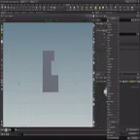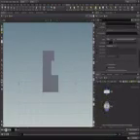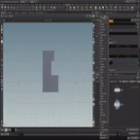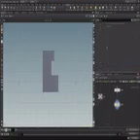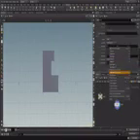Then I want to place a fuse, because we're gonna place all these points onto a grid. So let's set this to grid, and let's add a null node. And this null node is going to have the grid size. So let's call this grid size. So there we go. And let's set it to something like this. Let's copy this into the fuse.